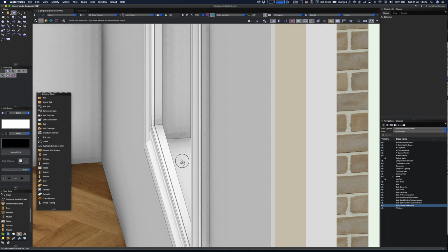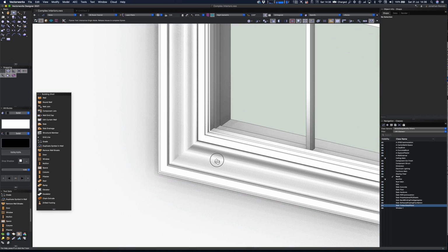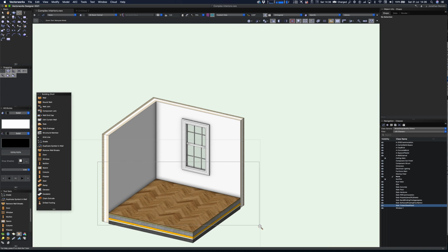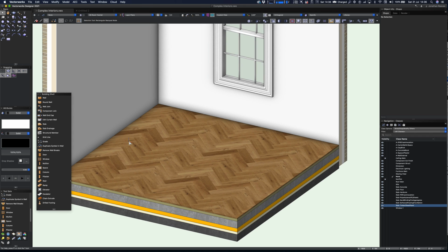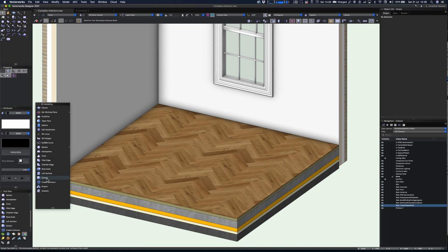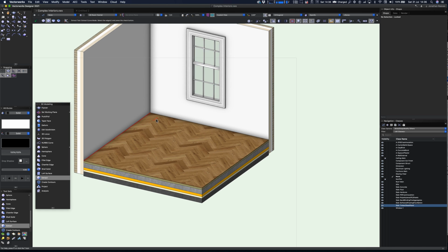You can see the lovely detail we've got from our extrude along a path, just to put some nice coving or mouldings around that window, as it would be in this fairly traditional design at the moment. Okay, that's good. So I think what we'll do now is go to our 3D tools. We're going to go to a tool called the Extract Edge tool. We're going to select those two edges and just click tick to extract them.